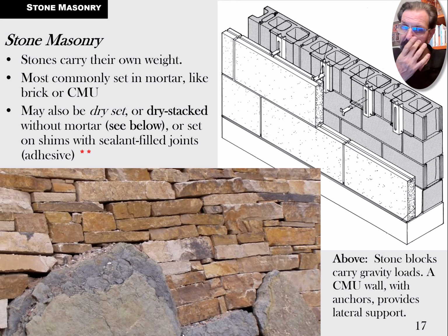You might not use something like that for a high rise. You might have to use a more reliable system because you don't want any of this stuff falling. But generally on a 1-story, maybe even a 2-story building, you can get away with something like that. It's basically another version of what we call a cavity wall. There's a cavity between the walls, and that allows the air and moisture to condense and collect and dribble out through weep holes down at the bottom area.